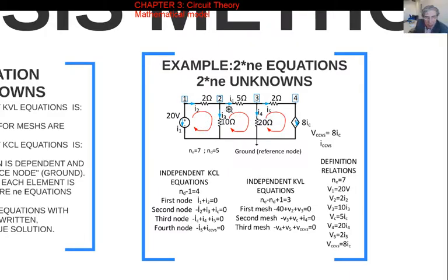What is added to this, I mark the nodes 1, 2, 3, 4, and also I put these current references to these elements. You see, all these blue ones have been put later on, and these meshes have also been marked afterwards. This mesh is not normally marked as it is done here. In the original circuit this is not there. So these mesh ones, these red ones, are the meshes, not loops. These are the special loops. In Turkish we call them göz.